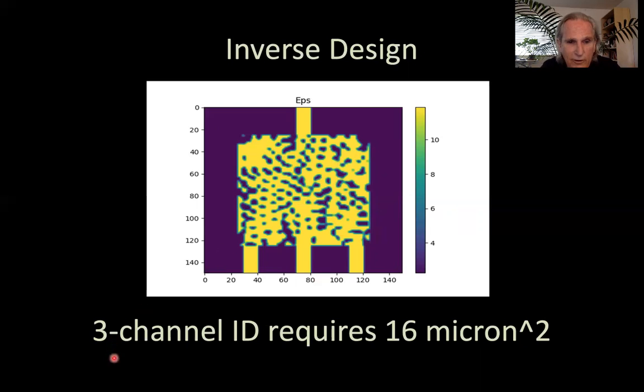We're starting to look at whether we can scale this up to large numbers of channels and still have this advantage. We've got these with like 6 channels coming out. I didn't have a good picture of one that seemed to greatly violate the diffraction limit by quite a large amount. And we don't know why, because if you look at this, you can't make head nor tail of this pattern, yet it works. It works quite well. The crosstalk here is very low, minus 20 dB, and the losses are very low also. These are matched to well within 1 dB at the output.